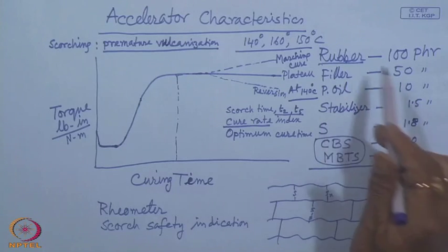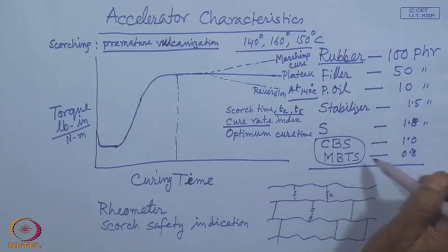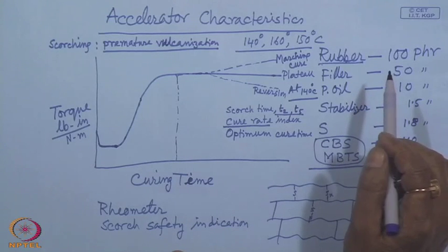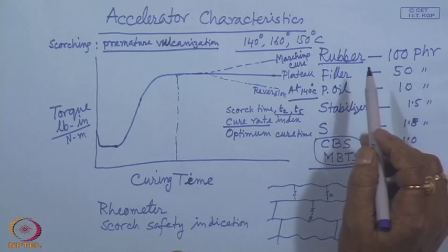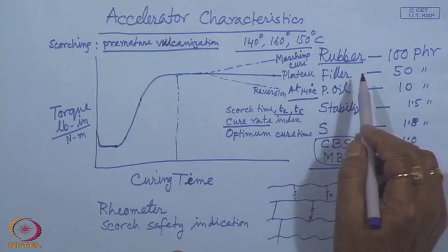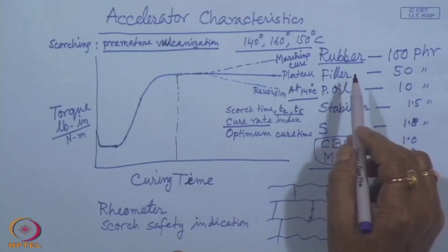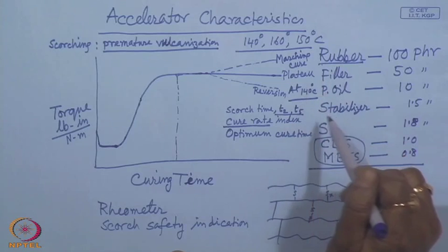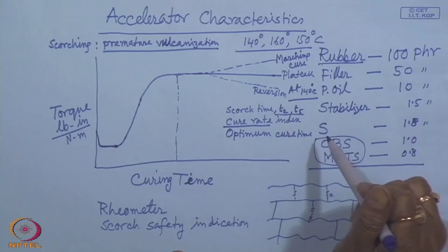Not only that, after compounding, that rubber compound is used for fabrication to give a shape to that product, say making a tire product or making a tube or making a profile. So, that passes through some machineries, say extruder machine or curing mold, curing press, etc. So, during that period the compound should not start any premature cross-linking.